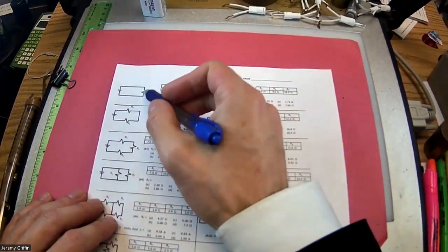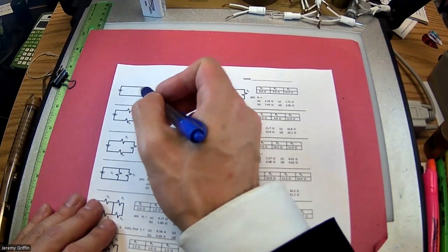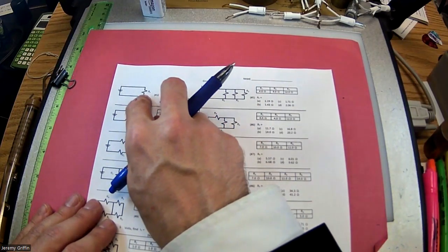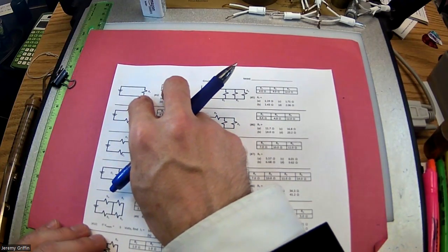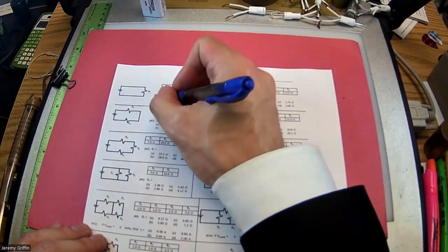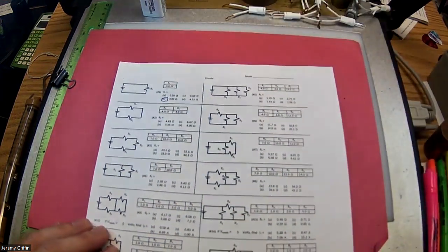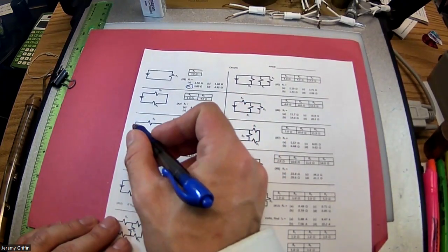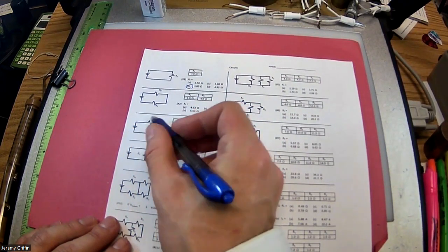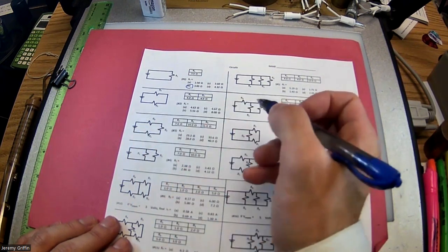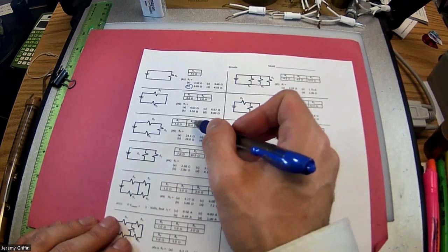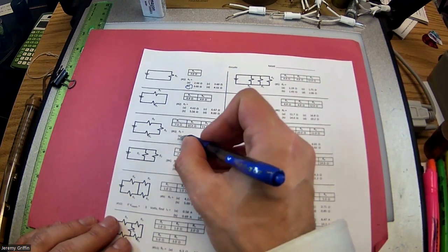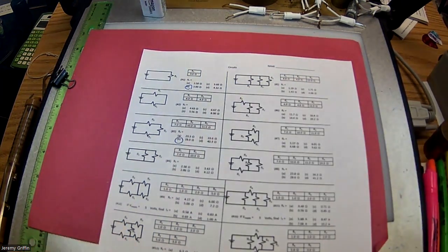Okay? If you have a voltage source and a resistor, the resistance for that entire circuit is the resistance of that single resistor. So does that look like 3 ohms? Do you guys think 3 ohms in that case? Right. If you see, let's jump down to this one. You guys see 3 resistors in series. So the total resistance, you just very simply add up the resistors. So 7 plus 10, 17 plus 11, it's like 28. You guys see 28 ohms total resistance?